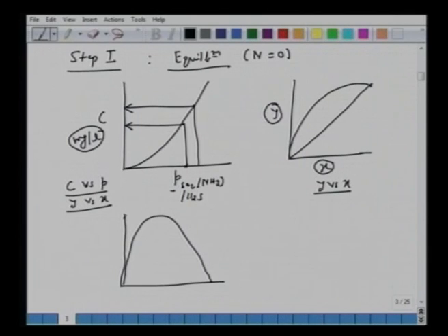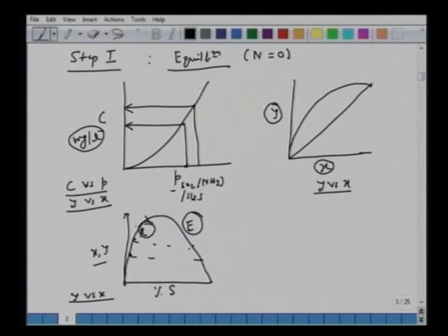So we said, percentage amount of solvent S, and here we can have x and y as in extract phase and the raffinate phase. We need to know what the equilibrium concentrations are. So they connect here between this. So this is also about y versus x in two phases, extract and raffinate.